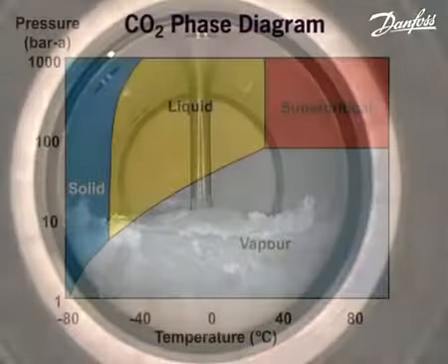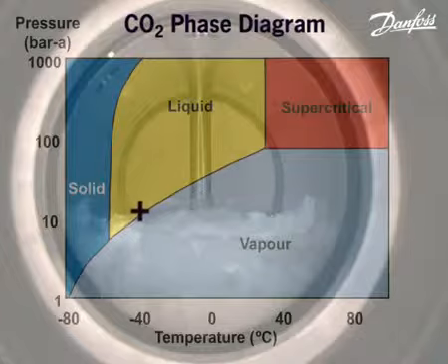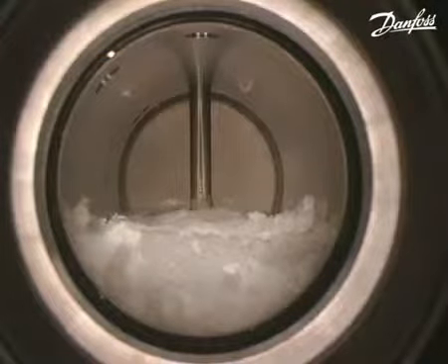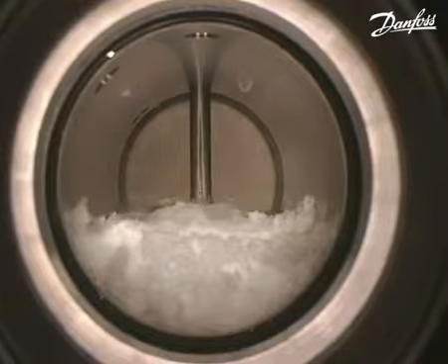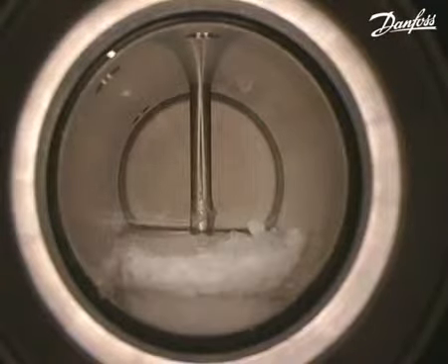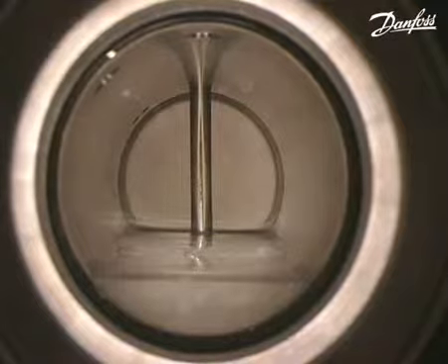The vent valve is closed. The entire cell is now below ambient temperature and will absorb heat from the surroundings. Triple point conditions are re-established as the solid CO2 melts, and as the pressure and temperature rises, the cell contains liquid CO2 and vapor in equilibrium.